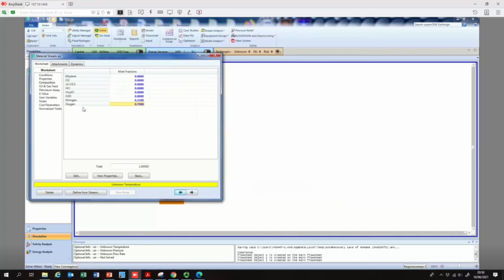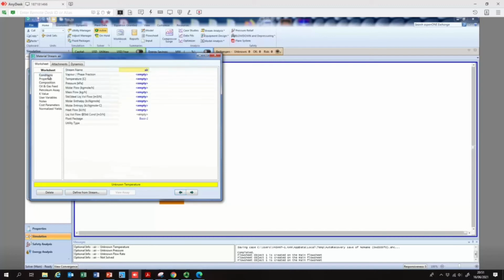We need only half a mole of oxygen. So 350 divided by 2, that is a very low number, it's around 175, I think. So we can set the flow rate of roughly 1000. That should be more than enough. We're supplying oxygen, in fact, in excess. 1000 mole. Then temperature, let's put the same temperature, 60 degrees. Pressure, let's put 1.5 atmosphere.